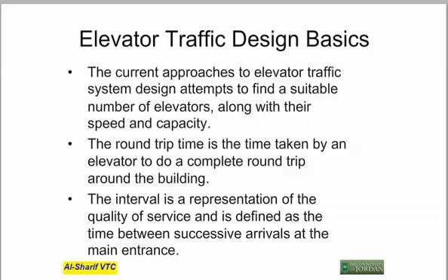Now, the interval is also an important parameter because it represents the quality of service, and it's defined as the time between successive arrivals of elevators at the main entrance. So if a passenger arrives at the main entrance and is waiting for an elevator, the maximum time that he or she would wait between the departure of an elevator and the departure of the following elevator is called the interval, and it's highly correlated with the waiting time that passenger would experience.